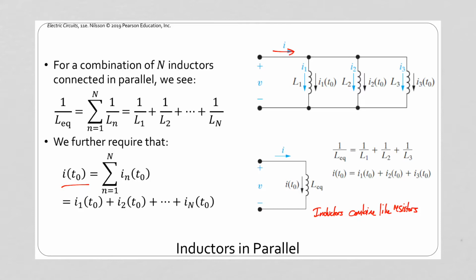The thing to remember from all of this is that inductors in series just add up. Inductors in parallel add up as reciprocals. That means that inductors combine like resistors. So we know how to combine resistors. Inductors are going to add their inductances in exactly the same way.